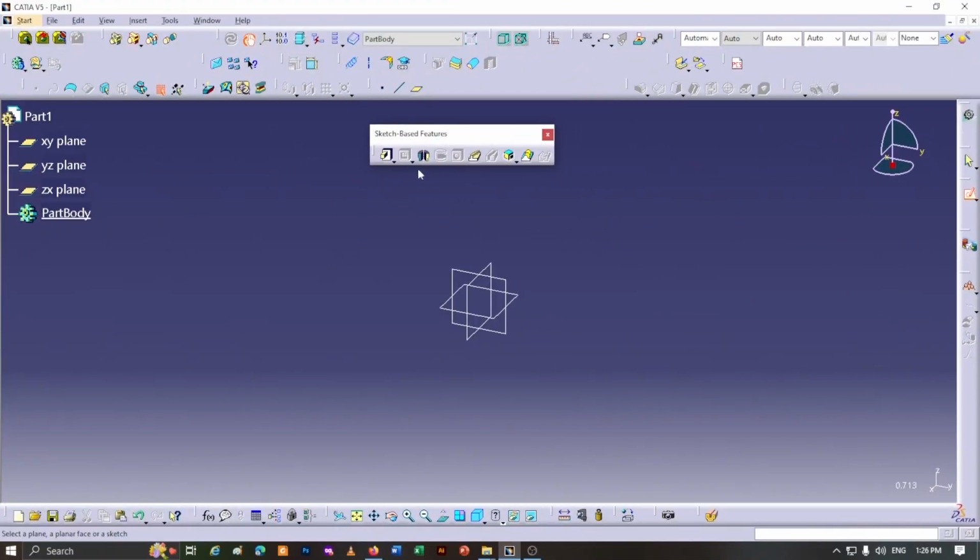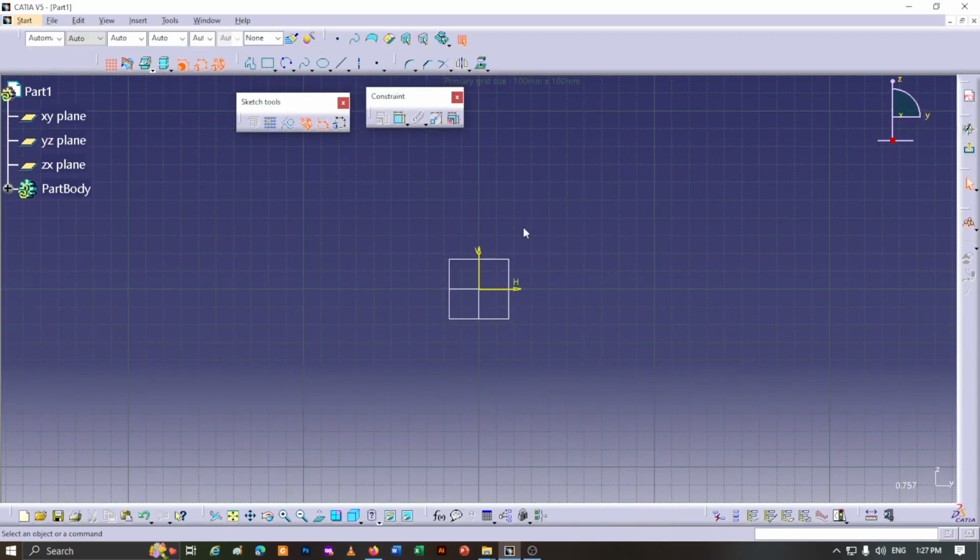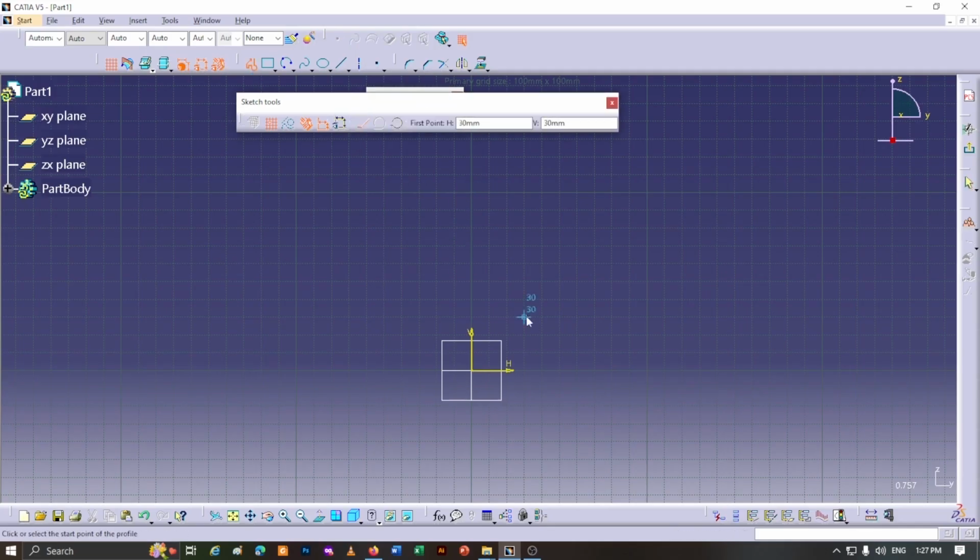Hello everyone. Today we want to examine the 3D modeling tools called shaft and groove. Many times we want to create a volume whose various sections are circular. In this case, these tools are suitable. I am currently in the part environment. I select a plane and go to the sketcher environment. To draw more accurately, I activate the Snap to Point command. I draw a profile.